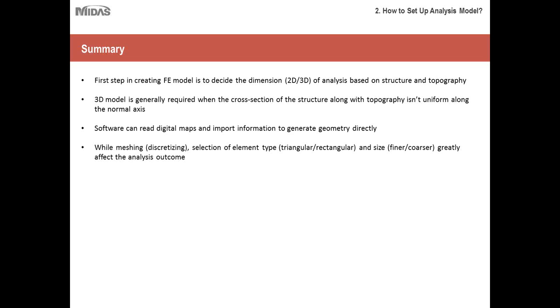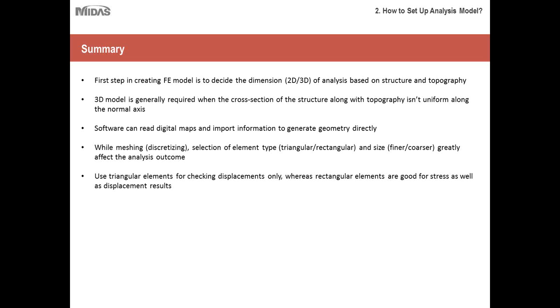And then while meshing or discretization, selection of element size, whether to use triangular or rectangular elements, and the size, whether to go for finer or coarser mesh, it greatly affects the analysis outcome. Use triangular elements for checking displacement only, whereas rectangular elements are good for stress as well as displacement results.